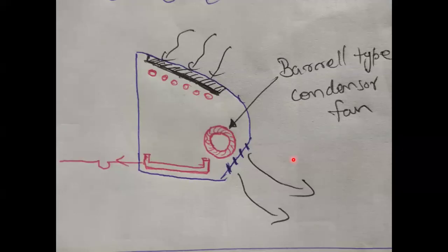Then inside these high wall split ACs, how is the air replaced again and again? As I mentioned for the window AC, the existing room air is pumped through the return air grill and comes into contact with the evaporator coil. Here also you can see the drain, isn't it? Drain means the moisture content in the air, when it contacts the evaporator coil, condenses. That condensate is termed the drain water. On the bottom of the indoor unit we have a drain pan, attached to the drain pipe connection, which is terminated outside.